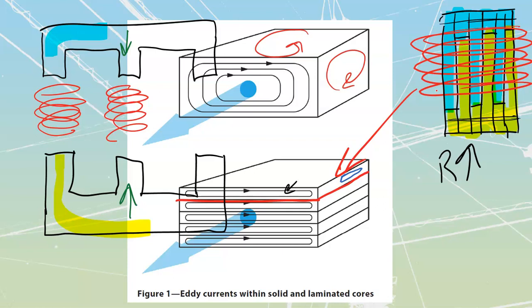If we go into higher voltage, we're going to have a stronger type of insulation between the windings. They call it a dielectric in a lot of cases because they don't want us to think about it as being insulation that prevents current flow. They want us to think about it as being something that is affected by the current flow. So they'll call it dielectric. It's the same thing. And they're oftentimes going to use oil impregnated paper. They take paper and wrap it around. The paper forms a physical barrier, then they vacuum in the oil. When they vacuum in the oil, it fills all the pores of the paper and gives you a really good insulation in between.